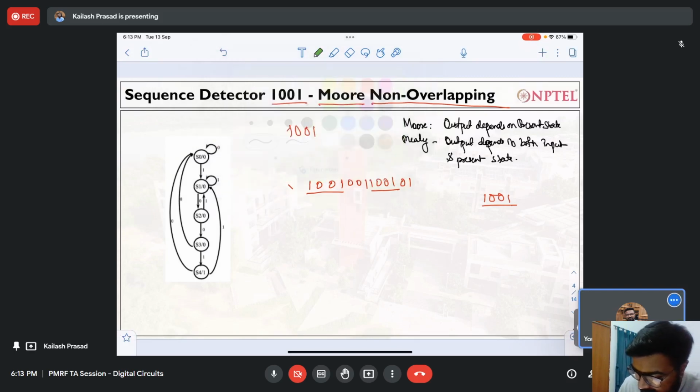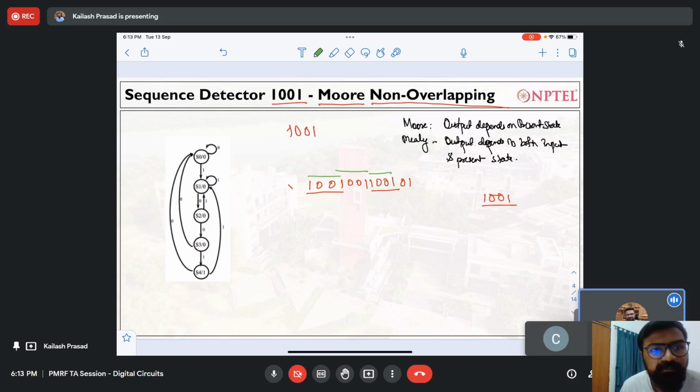So overlapping means that this is one, and again you see this one overlaps with this, but again this is a 1 0 0 1, and over here this is also 1 0 0 1. So three overlapping sequences. Now you understand: overlapping means whatever pattern you want to detect overlaps with the previous pattern. Otherwise, it's non-overlapping. In the first part, we want to detect a sequence which is non-overlapping, so we do not have to worry about overlap here.